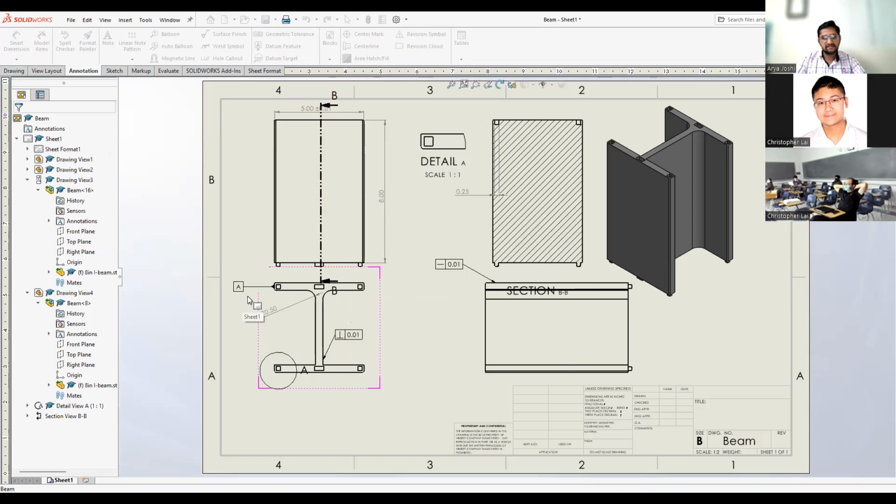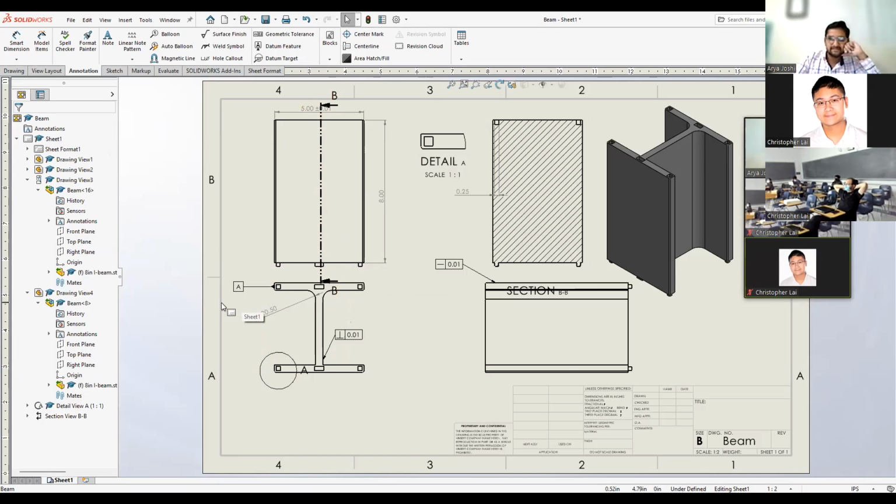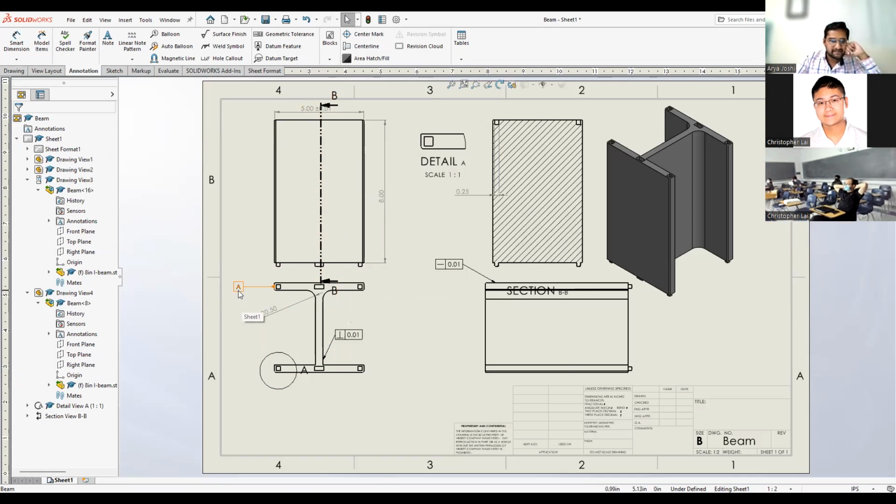Like I said, GD&T is very useful for subassemblies. The datums basically indicate where the parts are going to mate. So if a part is going to be attached to another part, exactly what surfaces is it going to be attached to, and that's what the datum would indicate. So we can use those to indicate those points.